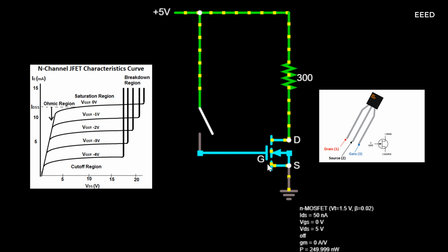This transconductance curve is important because it shows the operation of an N-channel JFET. You can also see that the transconductance curve, as for all semiconductor devices, is nonlinear for most of the curve, meaning changes to VGS do not directly, linearly, increase or decrease drain current, ID, even though this is a lesser issue.